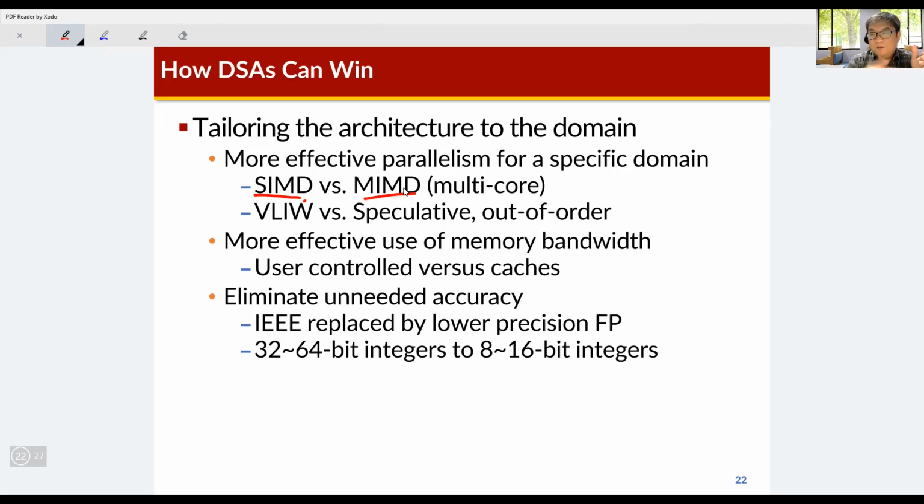But for domain-specific architectures, for example, if we design neural network accelerators, then we can design the cache and internal buffer structures specialized for data movement of matrix applications or systolic arrays. So based on specific data movement or structure of the data, we can design the specific architecture of the memory systems. That is also a benefit of the domain-specific architectures.